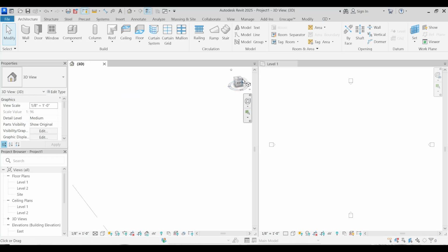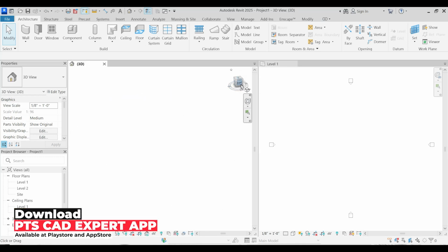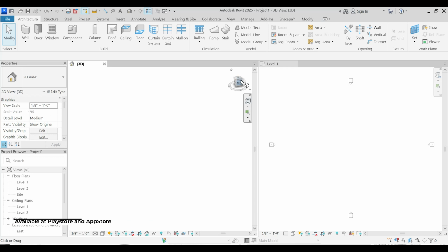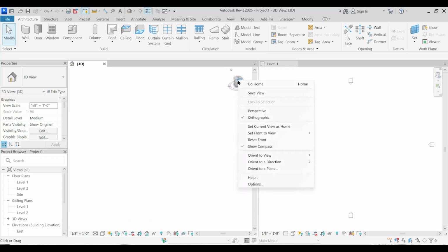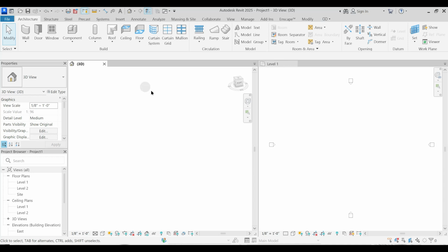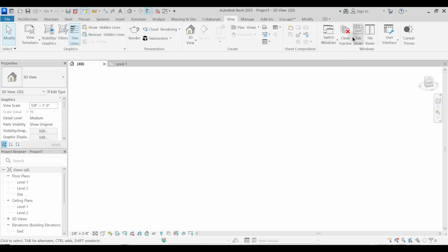Fine. And this view cube indicates top, bottom, left, right, and so on. But that's okay. Here it is, return. If you want the opposite of that, WT, TW. So that will open up this single view. Fine. WT is tile view and TW, its opposite, is tab view.